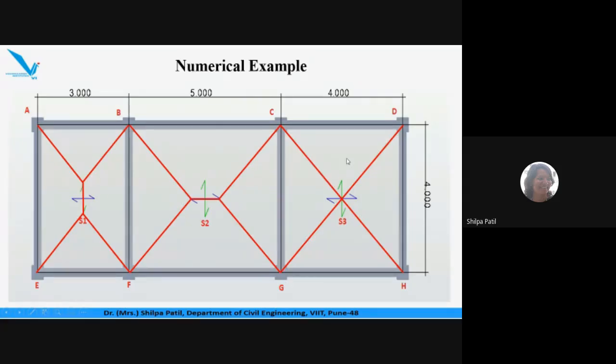And for the third slab, that is S3 slab, as both the sides are equal, the distribution lines simply cross each other, and for all the four beams, we have to consider the triangular portion of the slab, from which the load will transfer to the beams. So for CD span of the beam, from S3 slab, this triangular portion load we have to consider, which will be transferred on CD span.